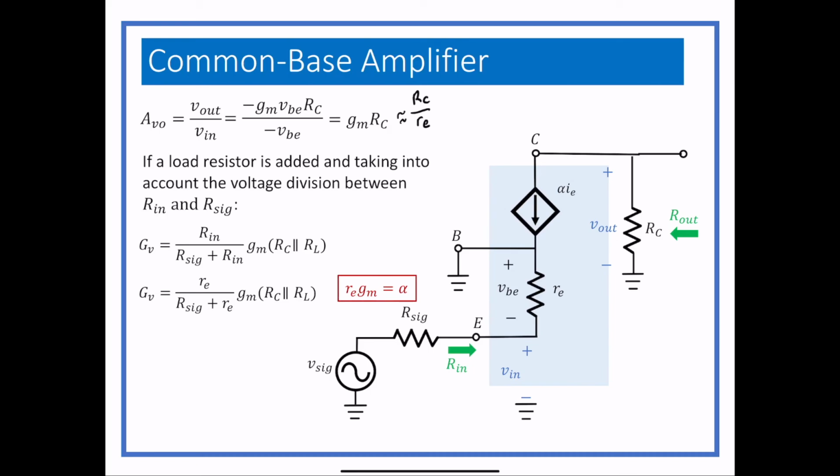So we can actually take the re in the numerator and substitute alpha, and we get this alternate equation to give you the gain. The top one will work, the bottom one will work. Either one will hopefully give you the exact same answer, we hope. You just often see, with BJT amps, the gain represented as ratios of resistors rather than using transconductance.